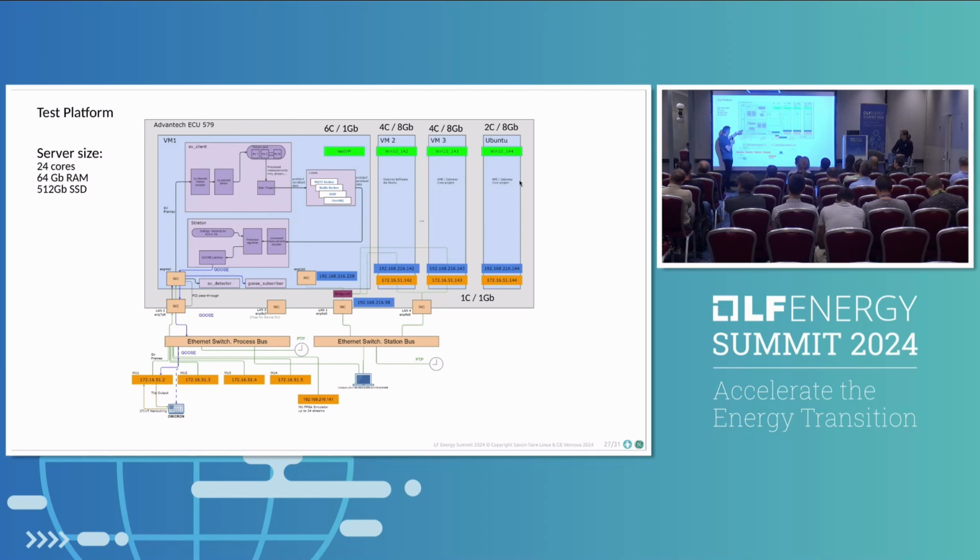All the data goes to an application in charge of reading those digital values. We call them sample values in our environment. Reading those sample values, we are calculating the RMS, phasors, the harmonics, etc., and we are publishing the data in a broker.